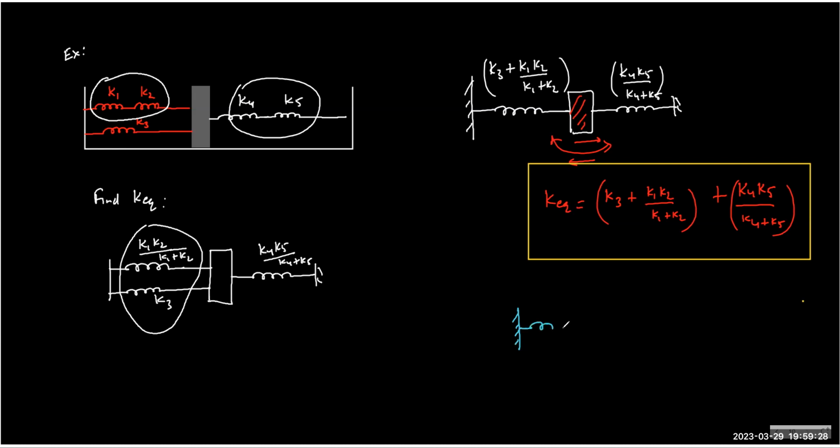So what we do is we replace all springs by one equivalent, and then we have just one block, and from here onwards we solve the problem. That will reduce the entire effort tremendously. No need to solve things separately. So I will first reduce to this section, and then I'll think about my work energy theorem or something like this.